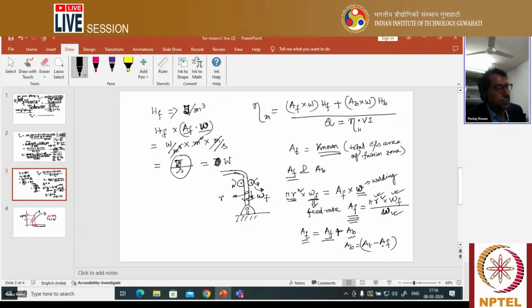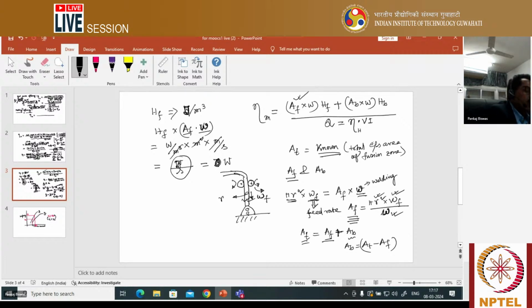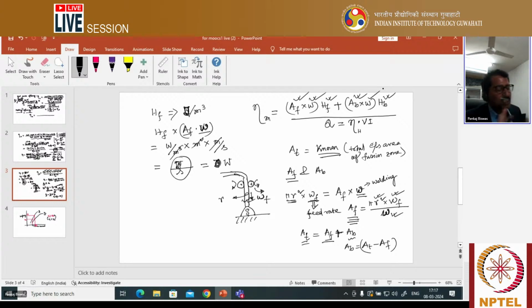Now I think it is very clear to you. So you now know everything. AF is known, AB is known, welding speed is known. What I am telling, understand? So all the things are known to you. If you know the heat source efficiency, the welding voltage and the welding current, you can easily find out the melting efficiency. So this way you need to calculate melting efficiency.